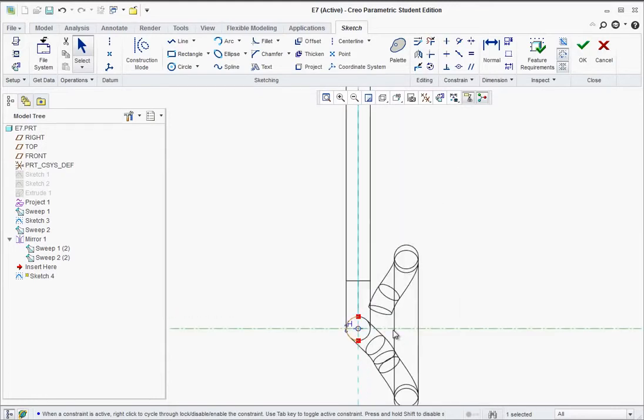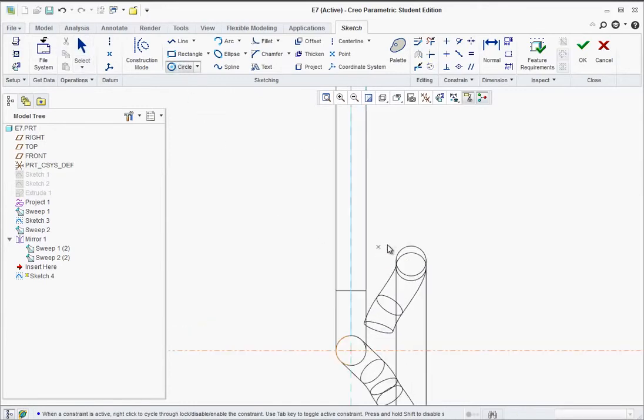So basically at this point, we're going to revolve around that in a second once we draw the circles. So go to the circle tool and start the first circle on this side. Remember, the circle is going to be where it starts bending in, down. So it's on the bottom versus the top here. We don't want the top. So right about here, click and drag out a circle.